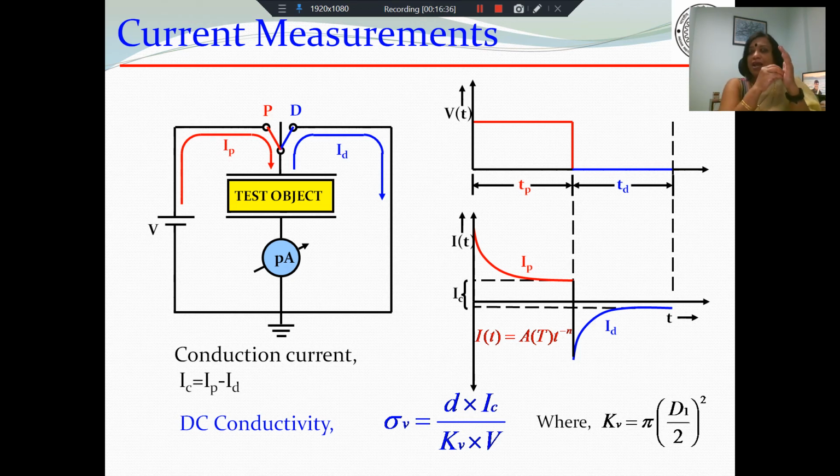They will cease to be aligned in the direction of the field. They will regain their random arrangement, and the dipoles which are not permanent dipoles, but the induced dipoles, the dipoles in the material which have been induced due to the application of voltage, will lose their dipole property. So whatever polarization mechanisms have come into play on energization will now be released.